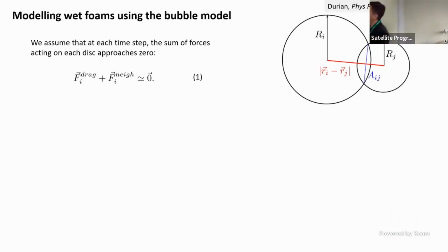The repulsion you can think of as a spring-like force. So the spring coefficient is given here as sigma 0 times the average bubble radius. Sigma 0 is just surface tension. Well, we have a dimensionless measure of the overlap and the direction of the force. So for the simulations I'm going to show today, we're not going to impose a flow.